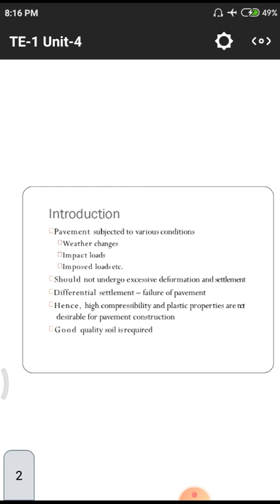if there is no proper kind of rolling. Normally, in the design of a particular road, we have to go for some quantity of rolling by using these rollers. Normally these rollers are used for the compaction of the road surface. Why? Because there are some strata, and in those strata there may be some amount of voids, layer by layer.